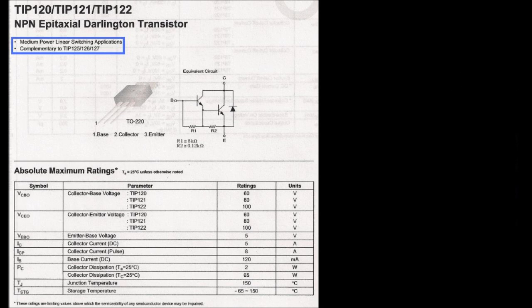Now, they all have the same ratings and everything. The only difference is they're opposite of one another concerning polarity. So you want to watch out what you're using and be sure you're using the correct polarity if you're replacing these transistors.